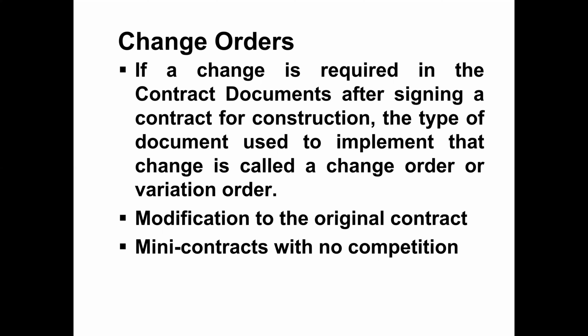But for all these things they have to do negotiation and agree, and every change order should be signed by the contractor, the consultant and the owner. So your last change order will be your last contract. Usually, any change after signing the contract will be in the form of change orders or variation orders. It could be a change in the contract document, a change in the time, or a change in the